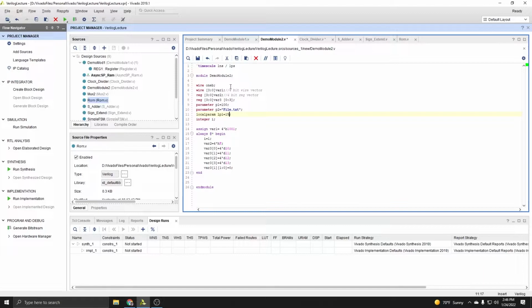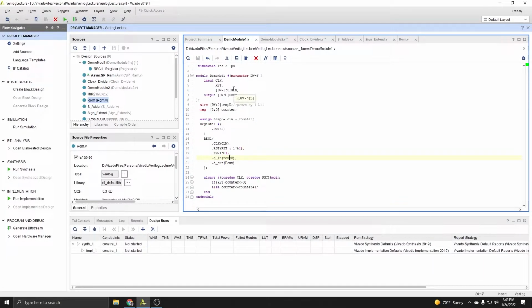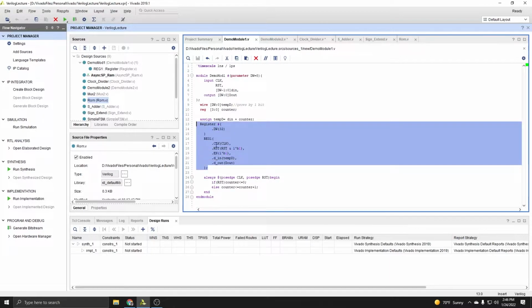I'll go a little bit more in detail when I'm showing you the actual Verilog code, but the main difference between the wire and the reg is that the wire is used when you're assigning to that variable outside of procedural blocks, meaning when you're using things like assign statements, or like I showed off in the first module, the module instantiations.